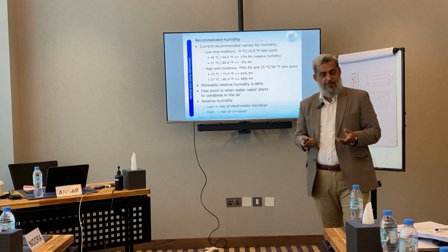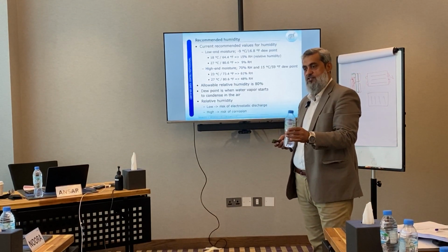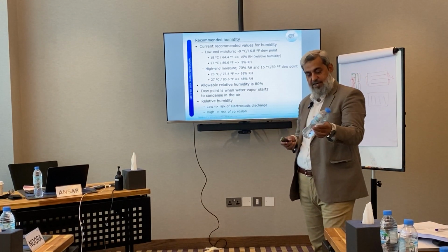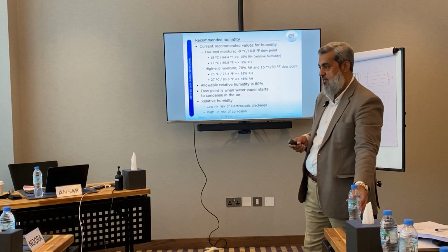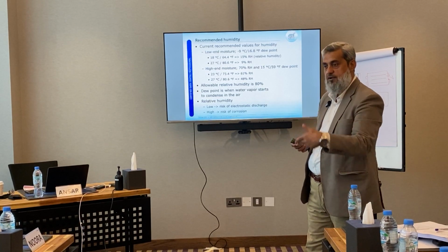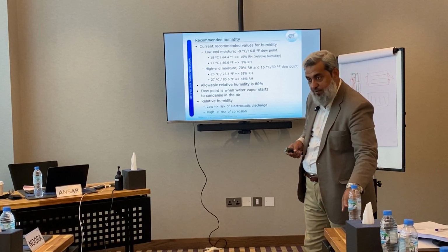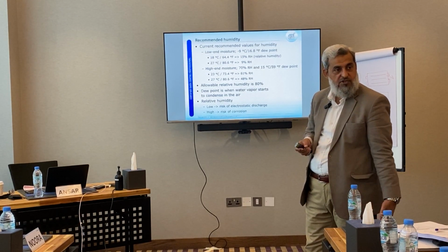The classic example is if you take this bottle of water, put it in the refrigerator, chill it, take it out, put it here. After some time, you will see water outside. Where does the water come from? Outside the bottle, it comes from the air, because at very low temperature at the surface of the bottle, air is not able to handle the moisture.